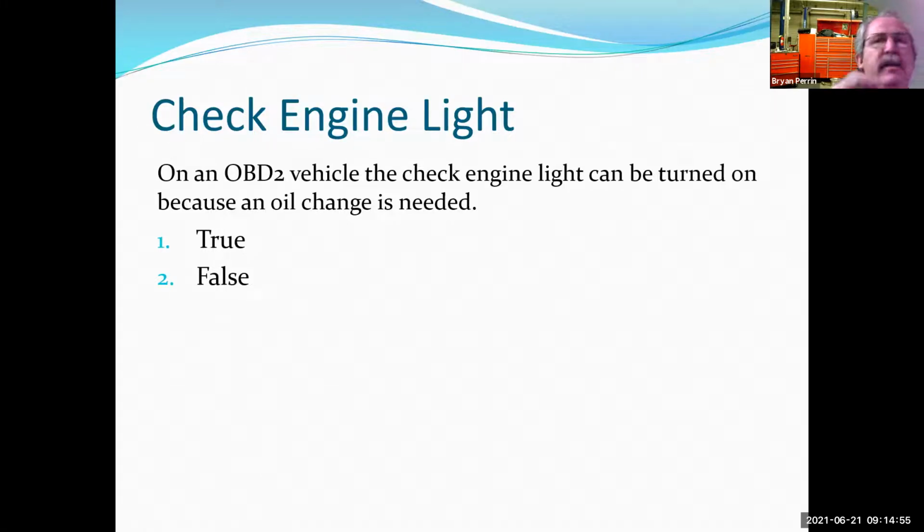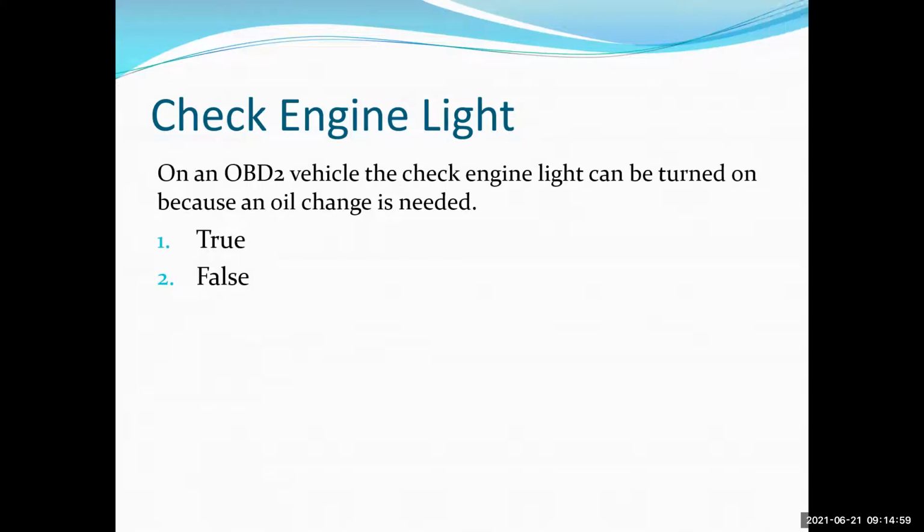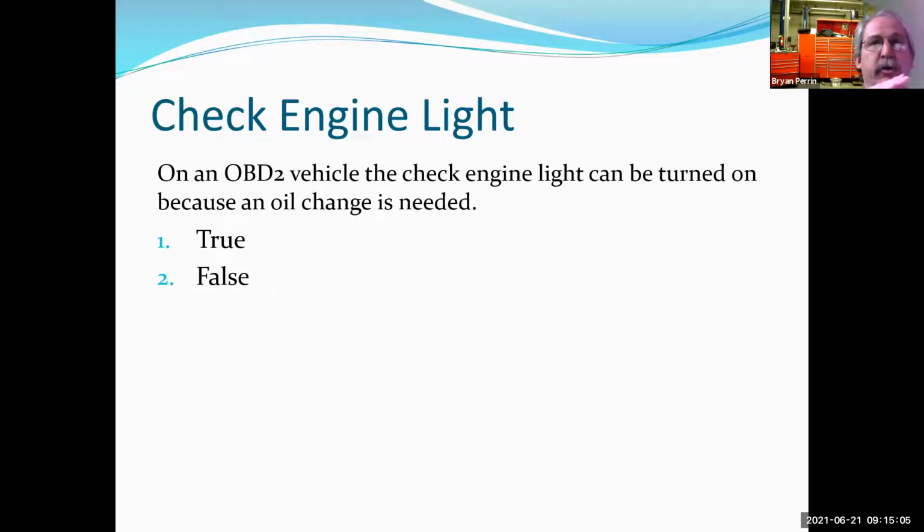Now, that being said, we do actually have codes that'll turn on the check engine light. Chrysler does this because someone puts the wrong oil in the car, or if the oil is extremely old. It has to do with viscosity and their variable valve timing system, how it works. If it's a delayed response or it's not responding in the correct time frame, it sets a code for wrong oil.